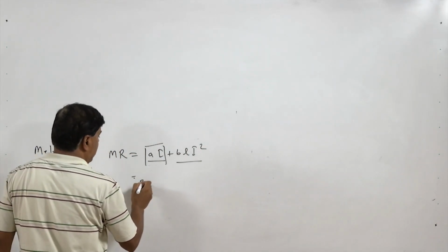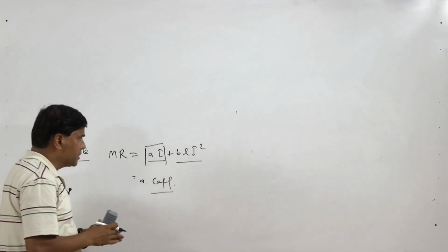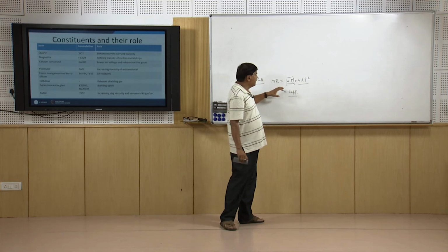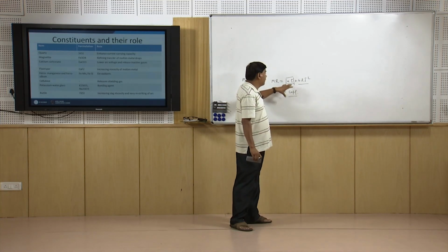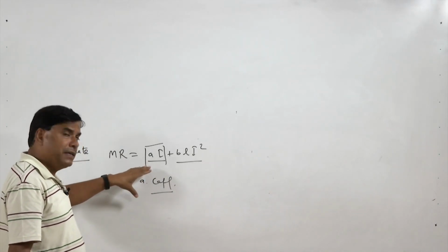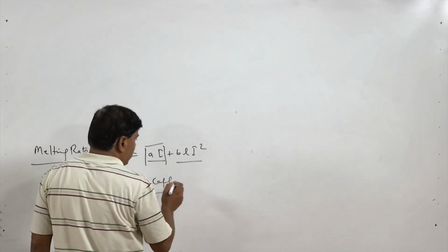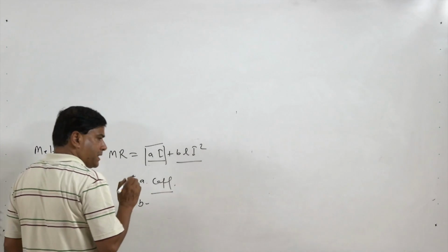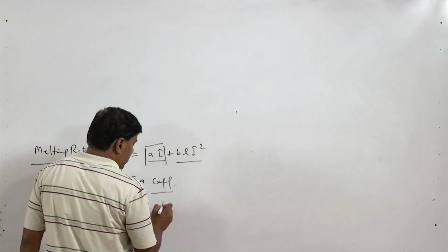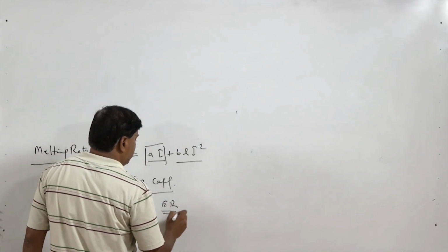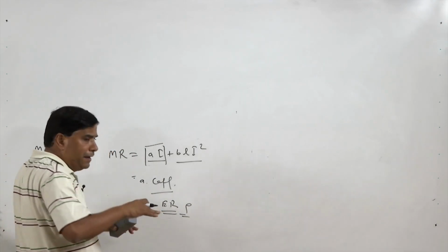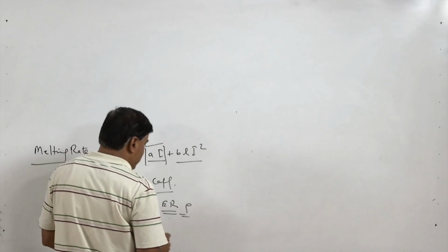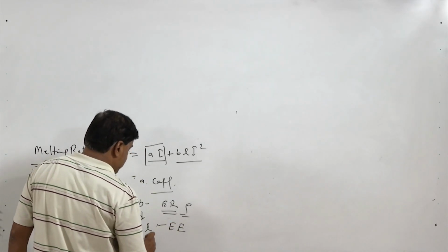Here, A is the coefficient or constant which accounts for the voltage drop in the anode drop zone or cathode drop zone, the chemical composition, and all those material and process related factors that affect the heat generation in the anode drop zone or the cathode drop zone. I is of course the welding current in amperes, while B is the coefficient for material resistance related factors, like the electrical resistivity of the metal, which is the big factor considered. So, high electrical conducting metals will have a low B value, while low electrical conducting metals will have a high B value, and L is the electrode extension and I is the welding current.